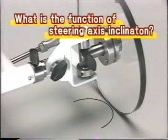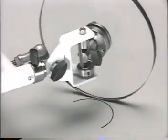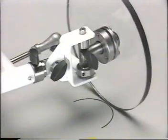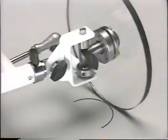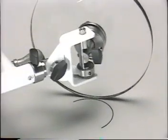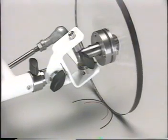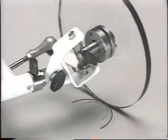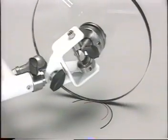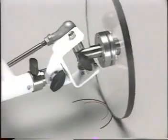Suppose the steering axis is vertical and camber is 0. In this case, the offset is large, so the vehicle turns in a large arc when the wheel's direction is changed. Because of the greater friction generated by the turning wheels, a greater effort is required to steer. On the other hand, if the steering axis is tilted and the offset is reduced, the wheels can turn in a smaller arc. This can reduce the effort needed to steer. Thus, one role of steering axis inclination is to make steering easier.